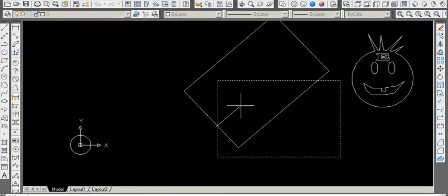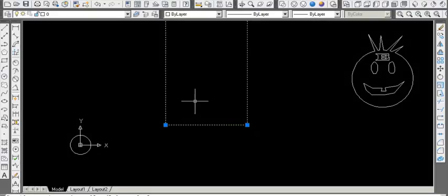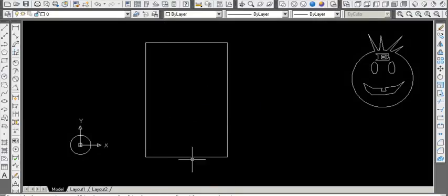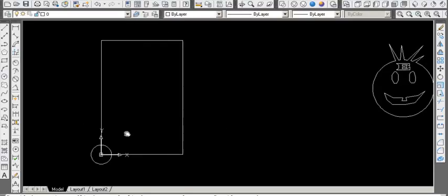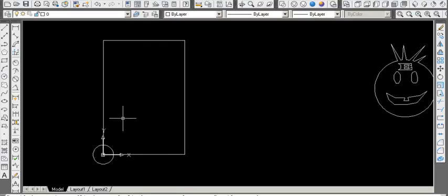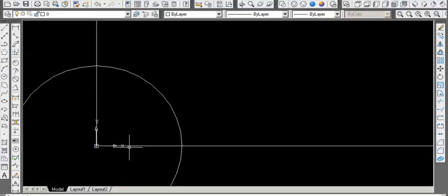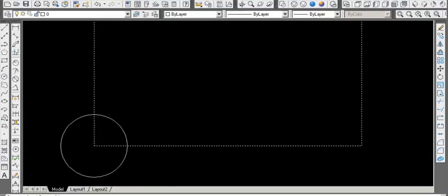I'll go ahead and rotate this just because I know that we like to use our plasma cutter running in the long direction. And I'm going to locate the sheet of material at the origin. I'm just going to use that circle I created to locate it there. Now with that in mind, this is my sheet of material. This helps me locate my origin, and if I were to zoom in, I know that the corner of my material, my plate, is at 0, 0.